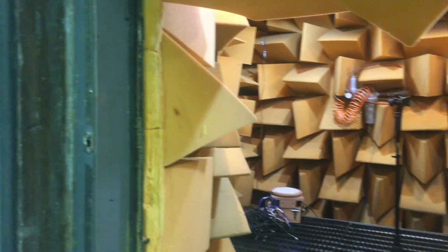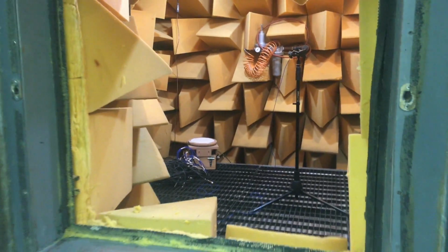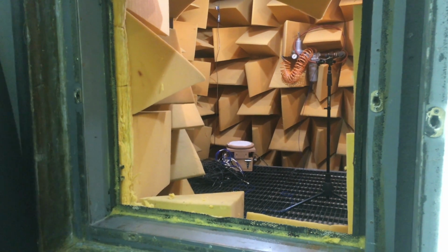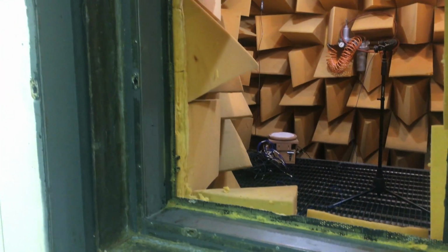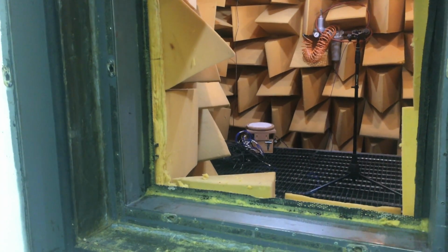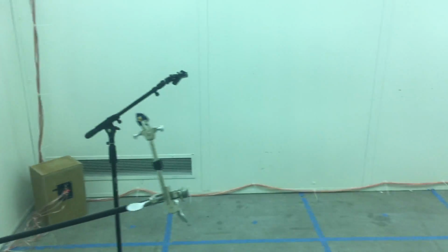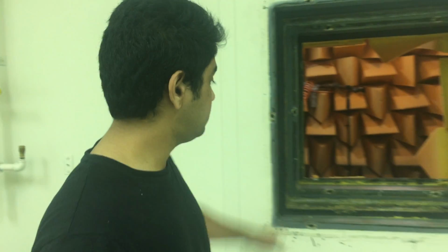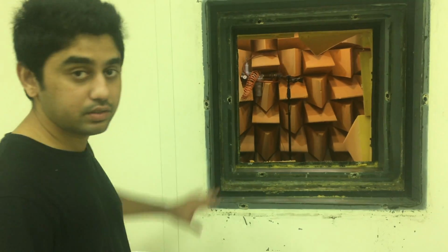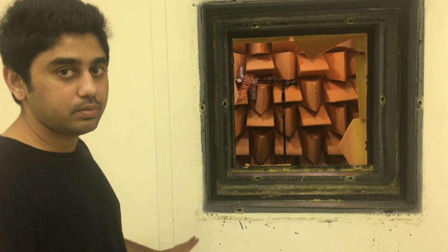So we're going to take the curtain material and put it up against the surface here and cover the opening entirely with 0% gap. We're going to use some tape to adhere it to the opening. We have a microphone inside the anechoic chamber and 3 microphones inside the reverberant chamber. And you should make sure that there will be no gap between the curtain and the wall, so that it will be a perfect condition.